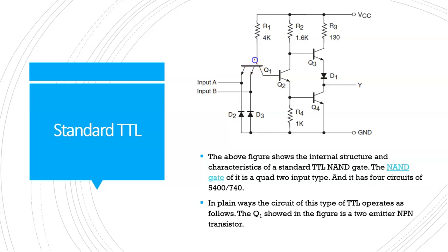So this establishes, just like a diode will be there, and here they're establishing a path from here to here. Voltage will be changing across these diodes, so there would be no collector current, and there will be no flow of current to the base of this transistor Q2. You won't be getting any current flowing to that one, and this is off.